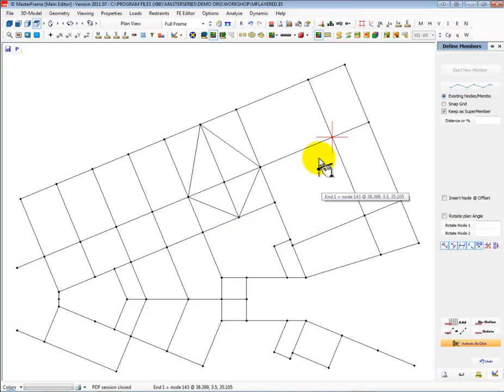So if I was doing this member, I could put a brace across here. If I kept those in and I want to put a brace across here, I could be at 6, 7 different points there, not exactly on the node. So place safe, put it in, and in it comes. So taking those out, naturally you all know that we can also put on member distances too, so 2 meters and 4 meters from either end of that member is available.